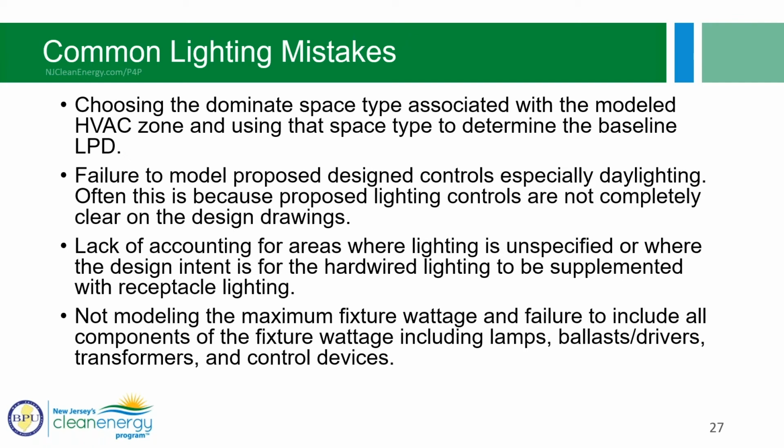Also, sometimes it can be finicky to enter them. We try to make it easy for you to go through your design and make sure you meet mandatory controls and to easily enter them in the compliance form. Another mistake is a lack of accounting for lighting that is unspecified. That's sort of a special case, so I'm not going to get into a lot of detail now, but that comes into play for dwelling units, hotel rooms, places where hardwired lighting is to be supplemented with plug-in